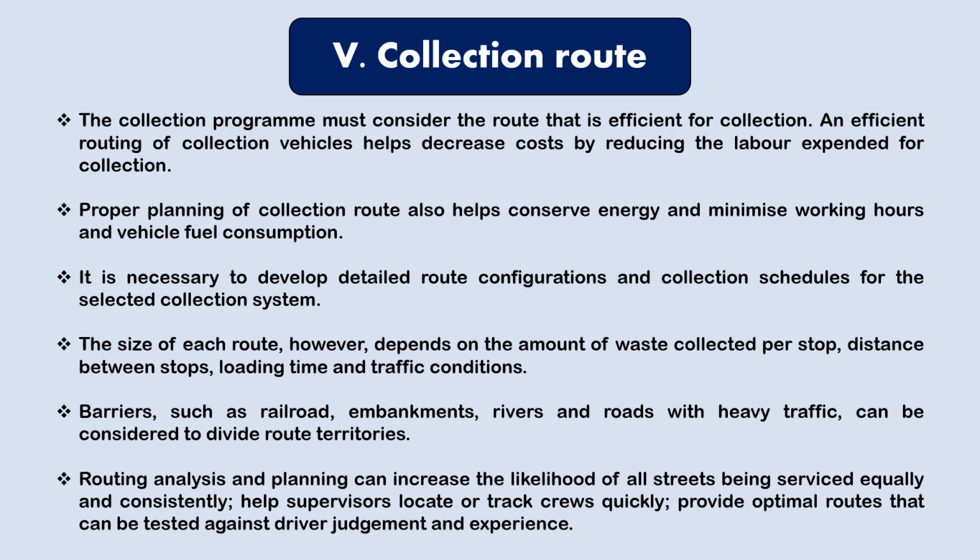So it's very necessary to develop a very detailed and proper route plan for the collection of waste materials. The route always depends on the amount of waste collected per stop, the distance between the stops, the loading time and the traffic conditions. So all these things determine the perfect route.